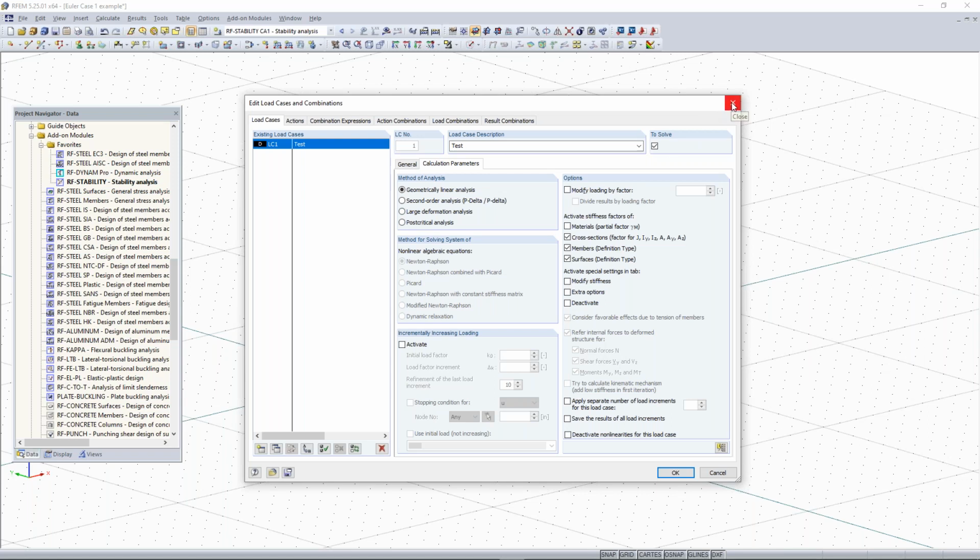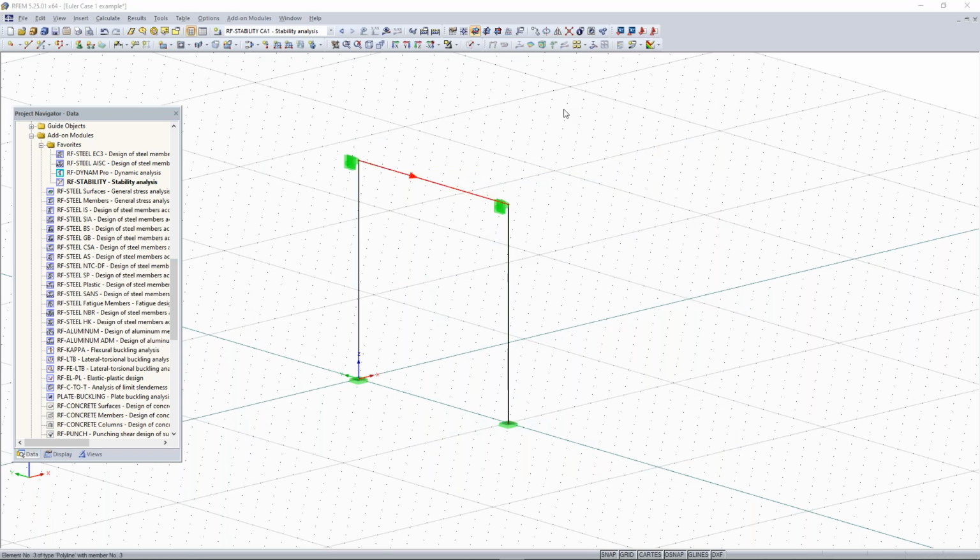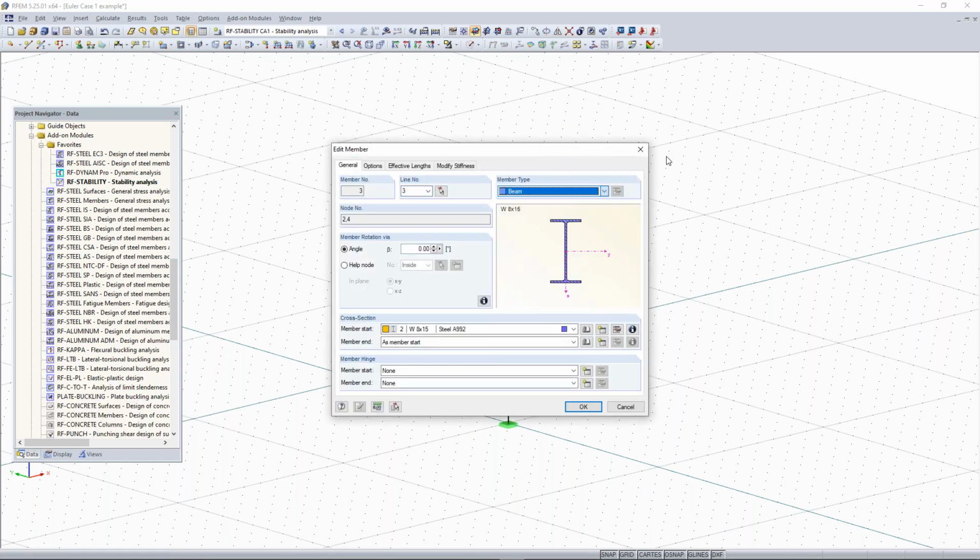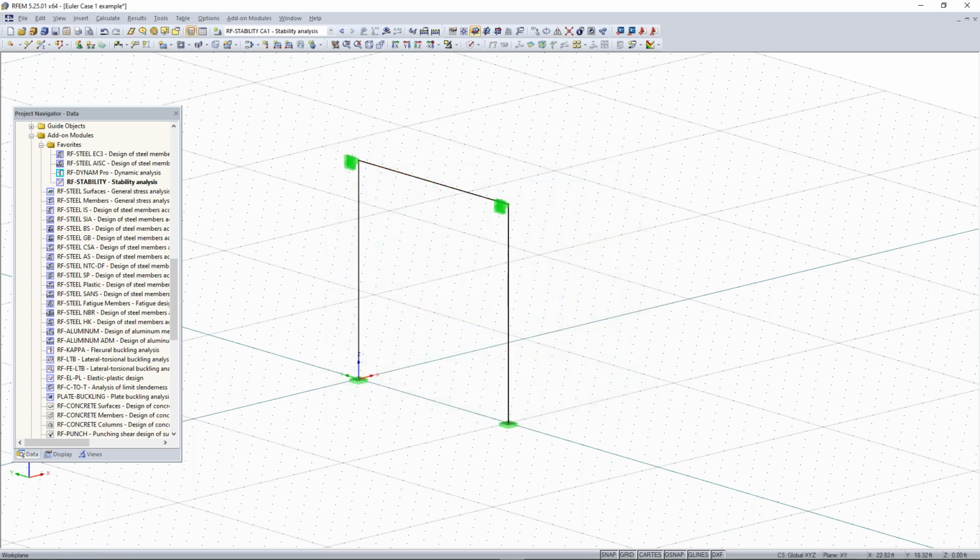Okay, so cable elements can be modeled within RFEM, as Alex mentioned. Automatically, the program will default to the large deformation analysis because we know with cable elements, they're a little special: the higher the tension force, the increased stiffness of the cable. It's important to know that if you use this cable element, you need to model it with the catenary shape in RFEM. If you prefer not to do that, you can draw it as a straight line and use the RF-FORM-FINDING module to apply a pre-stress force or a sag or a target length, and the program will come up with the catenary shape for you.